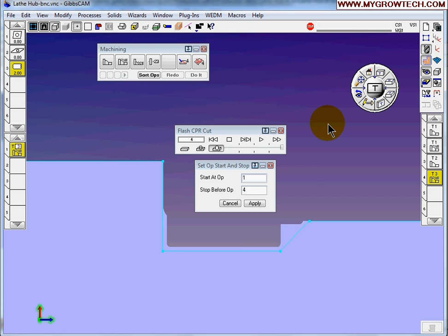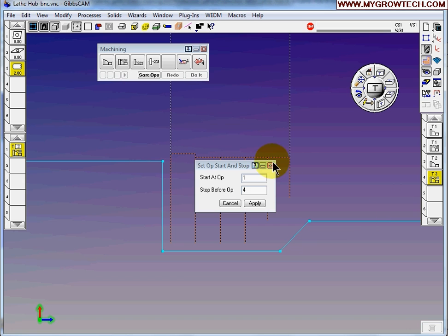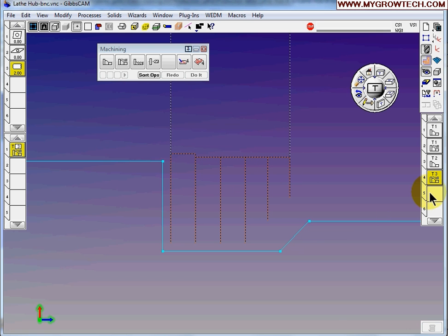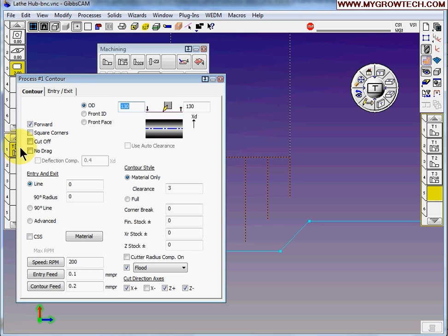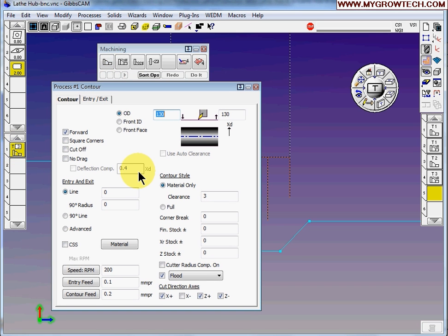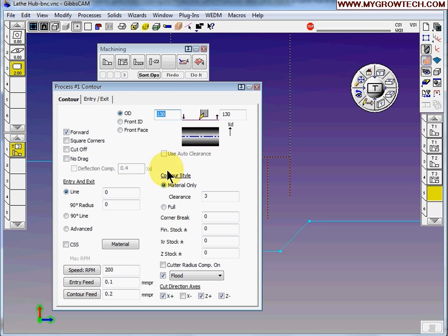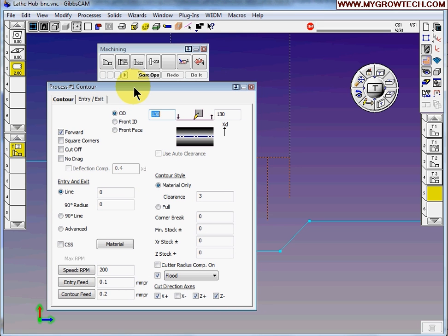Next, we're going to create a groove finishing process. And let's turn off the simulator. Make sure the fifth operation's empty space is highlighted. And now I'm going to do a contour process on the groove by using a groove tool, and make sure it's OD, the settings.